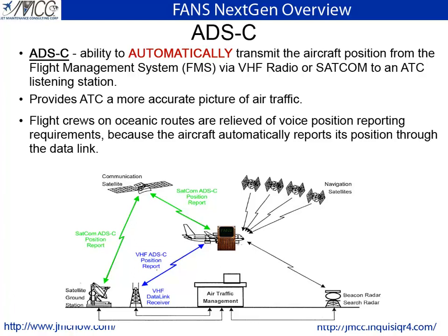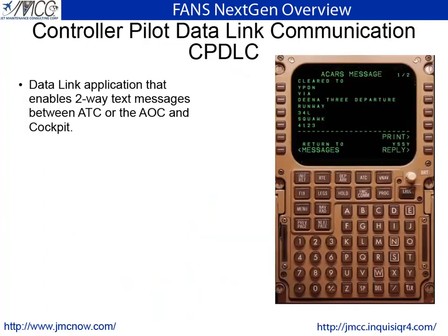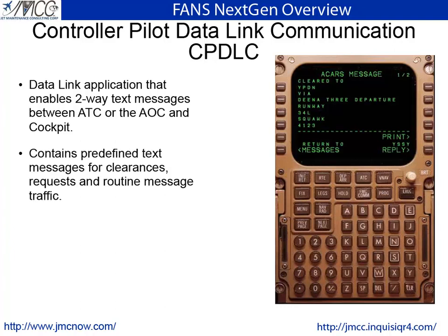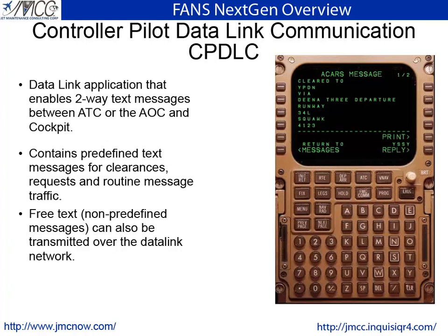Flight crews on oceanic routes are relieved of voice position reporting requirements because the aircraft automatically reports its position through the data link at predetermined intervals. Controller Pilot Data Link Communication, or CPDLC, is the data link application that enables two-way text messaging communication between the cockpit and air traffic control, or the flight crew and the airline operations center. It contains a set of predefined messages for clearances, requests, and routine message traffic.